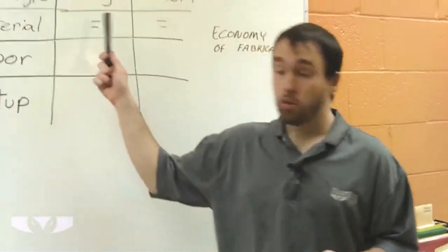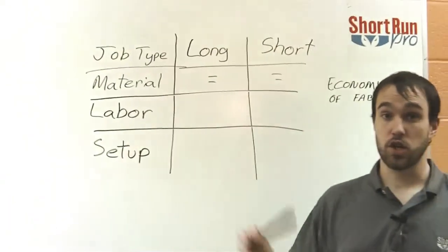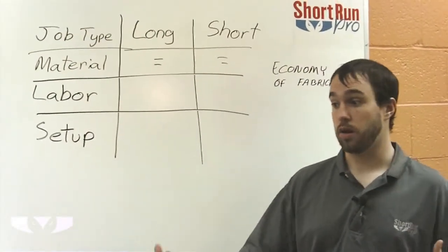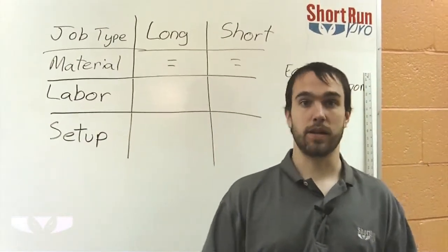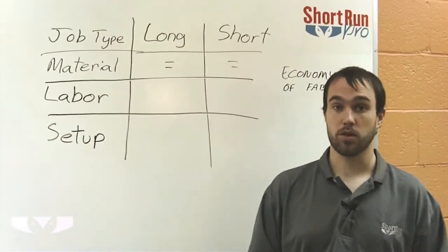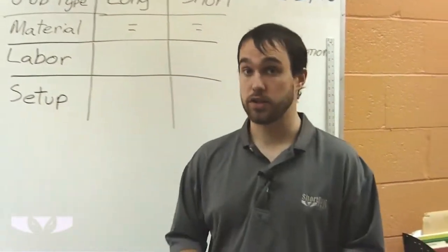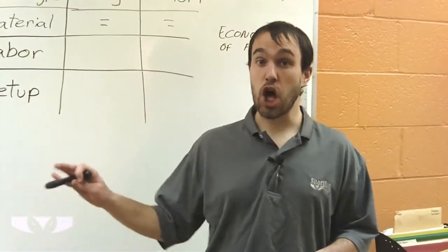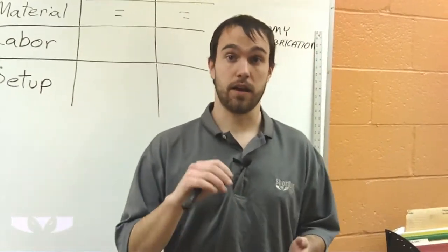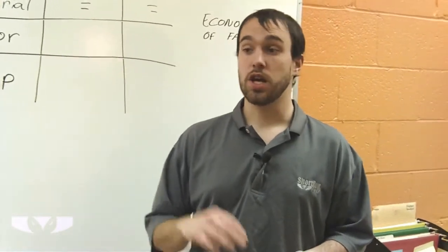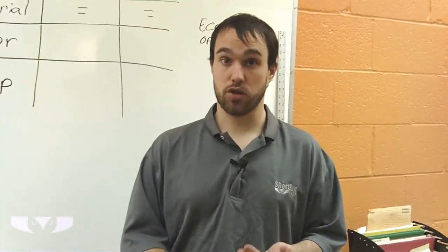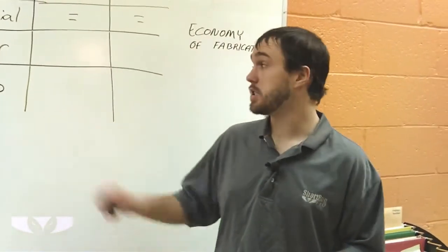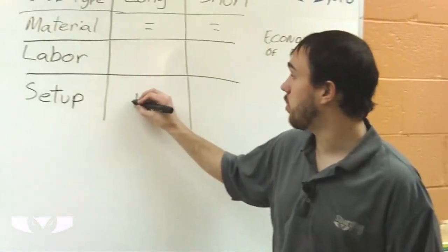Now, when you do long-run manufacturing, you make a special die or a special tool or mold, depending on if you're doing die casting or stamping or any of 100 different manufacturing topics. The key point I'm making here is it takes a lot of time to set up. You've got to have engineering to design the dies and molds. You've got to make sure those dies and molds are working properly. So there's a lot of setup costs, a very high setup cost in long run manufacturing.